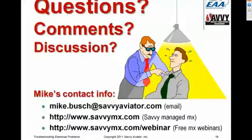Also, I think it's more important to use a trickle charger if you are using a sealed battery like a Concorde or an Odyssey than it is if you're using a conventional flooded cell battery, because the sealed batteries are less tolerant of getting discharged. We talked about this quite a bit in the webinar that I did on batteries. But generally, it's a good idea, and as I said, it's especially a good idea if the aircraft is based in a real hot climate.